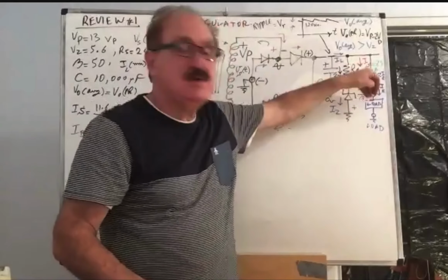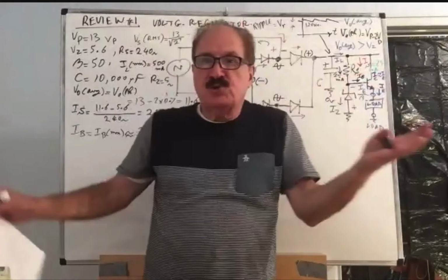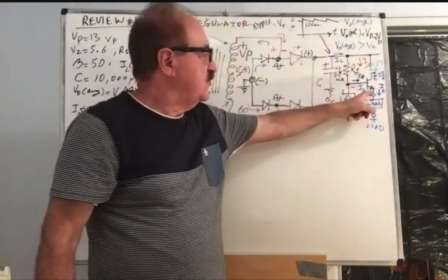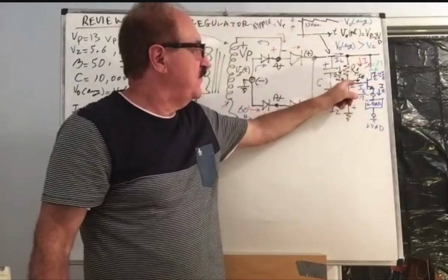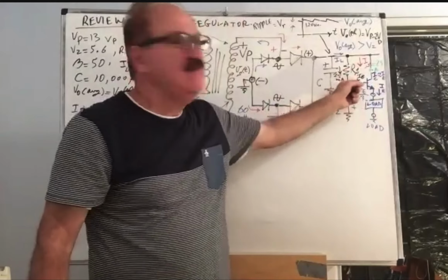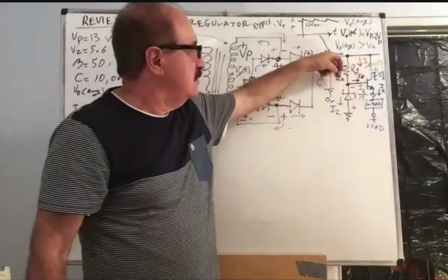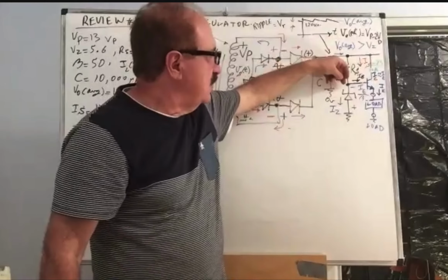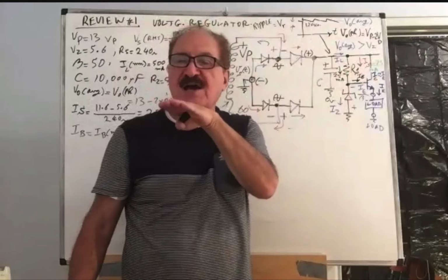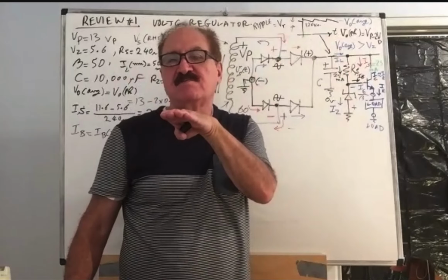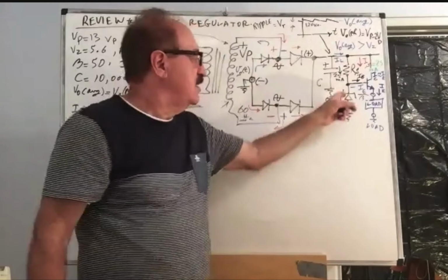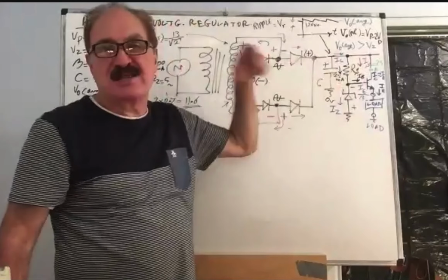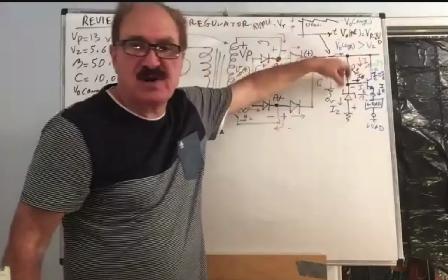So this base current is going to be top 10 milliamp under the highest pressure when you're drawing 500 milliamp. What if you don't draw any current, or you draw 1 milliamp? If you draw 1 milliamp here, you get 1/50th of a milliamp here, nearly like zero, and you're taking practically nothing out of here. All of the 25 will sink into the Zener, will give you a nice steady 5.6 volt. You won't even notice the change in the Zener current. So when it is no load, Zener current is at the max that you're supplying. The 25 will go there.